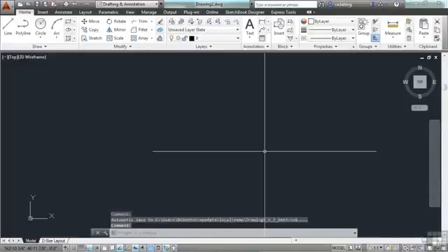a closed, multi-sided shape. You can create a polyline with several different commands: pline, rectang, polygon, donut, boundary, and even revcloud. Pline or p-line, depending on how you want to say it, because it's just the letter P, then L-I-N-E. That will be your most commonly used command to draw a polyline with. And we'll talk about the other options in a later section. Each of them have their place.